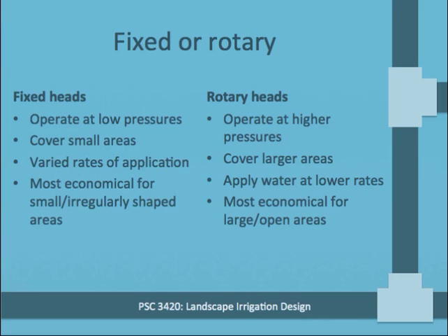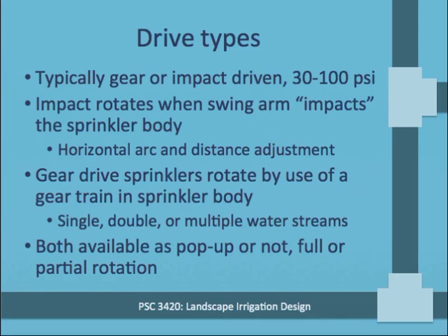Now, rotary heads typically operate at higher pressures, which means they can cover larger areas and they apply water at lower rates. The ratio of water application with rotary heads and fixed heads is that rotary heads typically, now granted I'm making a pretty big generalization, but rotary heads typically apply water half as quickly as spray heads. So that's something to keep in mind and is one of the major reasons that you don't ever mix those two heads on the same zone. Rotary heads are going to be your most economical choice for large open areas because you can get by with fewer heads to cover the entire area.